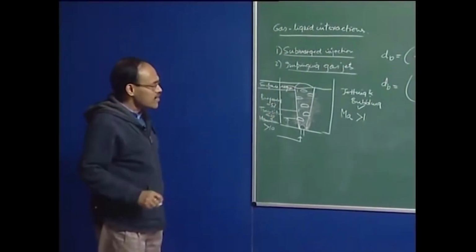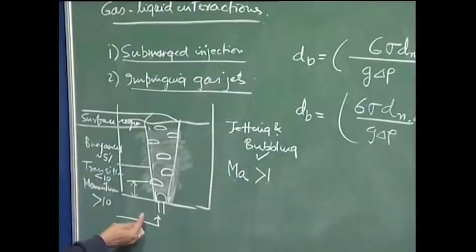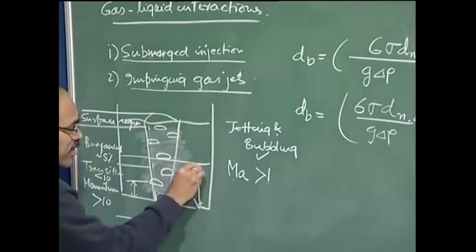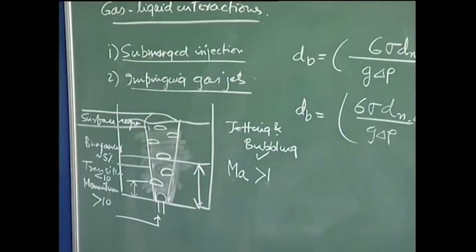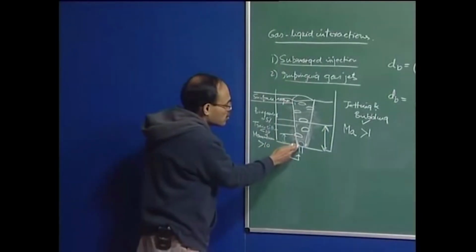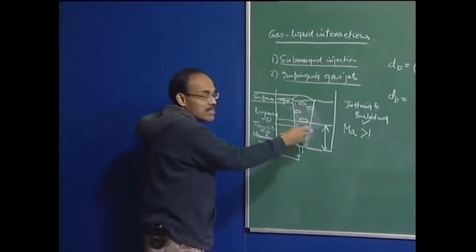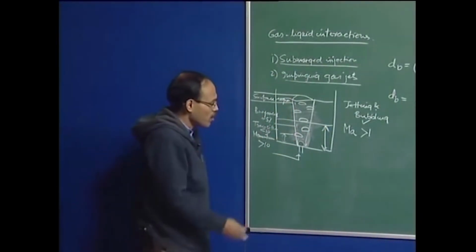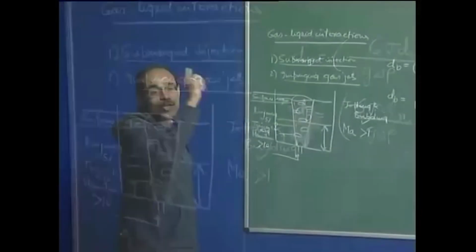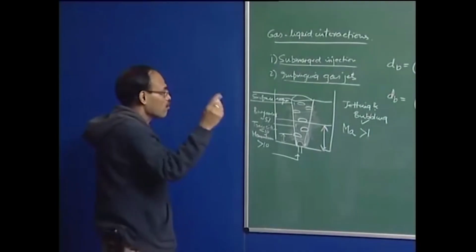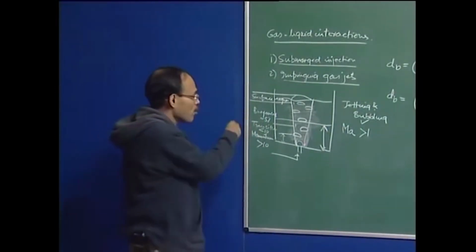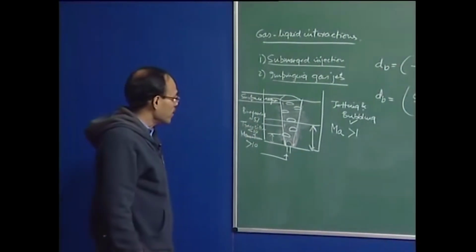One important characteristic comes when we are injecting a reacting flow into a small, shallow bath depth. Others have bigger bath depth, but when you have shallow bath depth, you have swirling motion. So even though this configuration looks like a two-dimensional or axisymmetric configuration, with shallow bath depth and injection at high rate, you can introduce a lot of swirling or rotational flows in the system, which can aid mixing in the process itself. And in OBM converters, this is very commonly encountered.